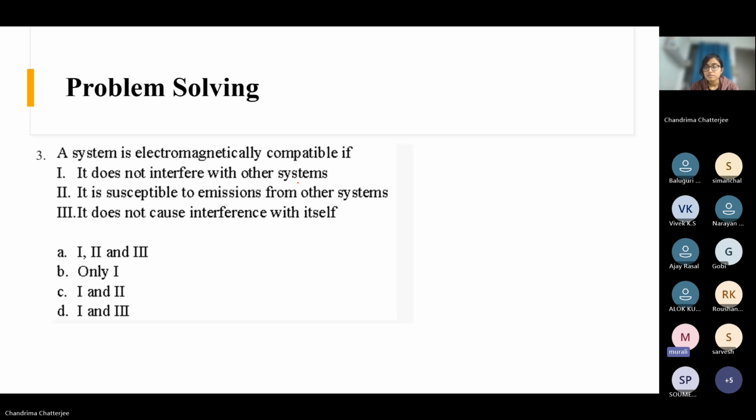That is the thing. Because I was in the TUV compliance while doing the testing, they have two electrodes which come near the device with a high voltage. They will check whether the device is grounded properly when it observes the high voltage. It should not affect the device.